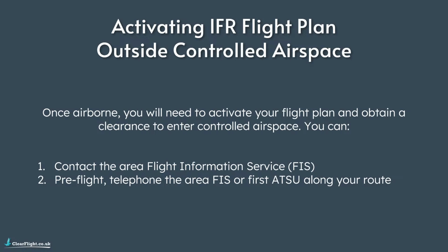But picking up the phone and ringing them can always be a good idea, because you can either get some information from them about who the best person to contact on the radio once you are airborne is to activate your flight plan, or they might just get things ready on their end for once you are airborne, so that when you do contact them on the radio, they've got a strip in front of them and they're ready to activate your flight plan and give you a clearance quite quickly after you first contact them.